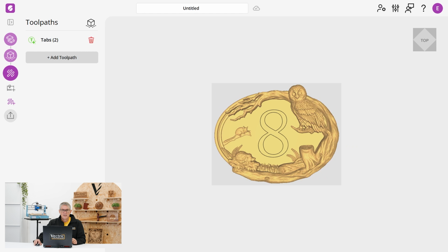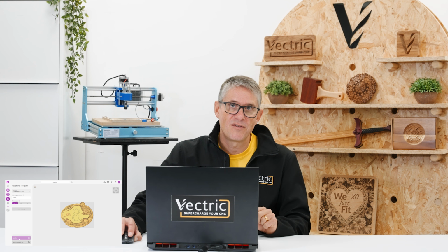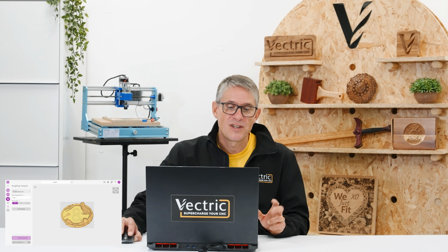So that's good. So I've got 2 tabs now, and now let's add some toolpaths, and let's do the whole lot, right? So you can choose your tools from the tool database. Again, this is all being selected by the material type. So the feeds and speeds here should all be pretty good. And just as you'd expect with Vectric, we allow you to manage all of this stuff very, very carefully. And we also assist you to make sure that you try not to make too many errors.